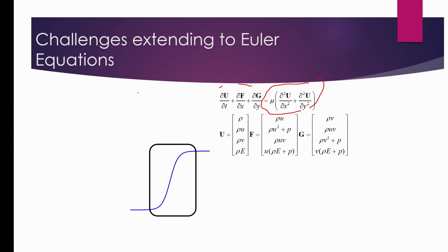The moment we add some viscosity to this Euler equation, the shocks will spread over several grid points. Once the shock becomes a little bit smoother, it will not give an infinite derivative value. This is the principle behind all the numerical schemes as well as PINNs, which we already discussed in the Burgers equation.